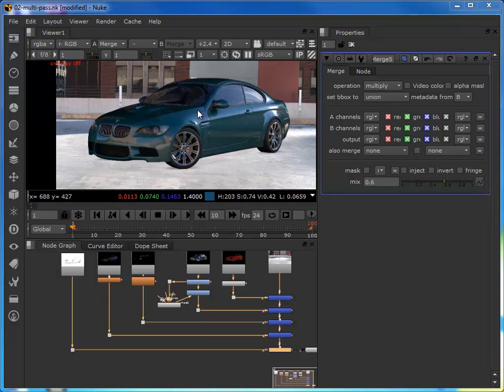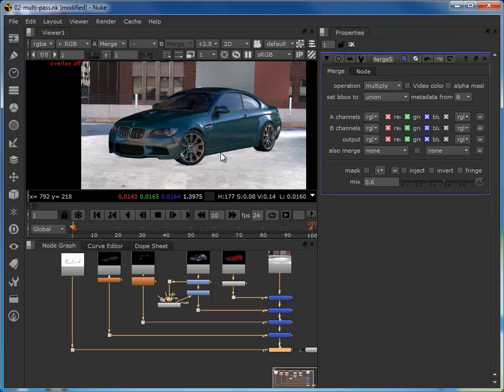So overall, we've made quite an impact on this particular image. It started off a maroon coloured car, and we've enhanced its specularity. We've controlled its reflectivity. We've controlled particular parts of the reflectivity so that we could colour tone these reflections that were in the front of the bumper. We've blurred and reduced the refraction effect. We've lowered the ambient occlusion, and we've tone matched the specularity to the environment.